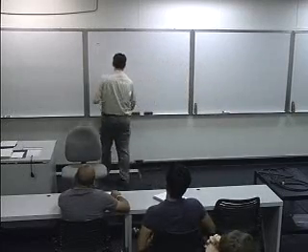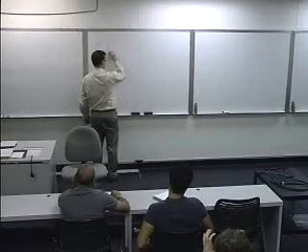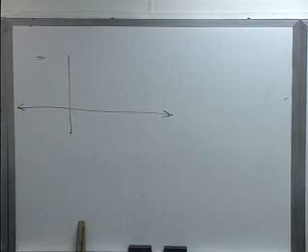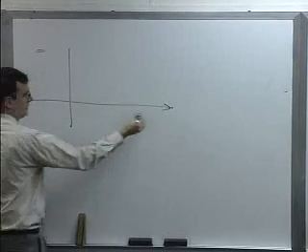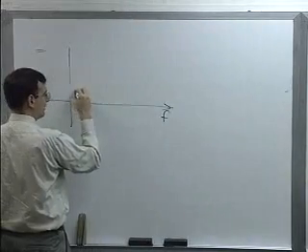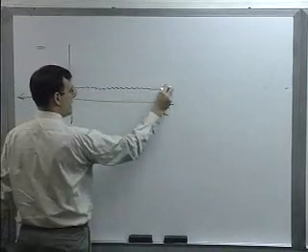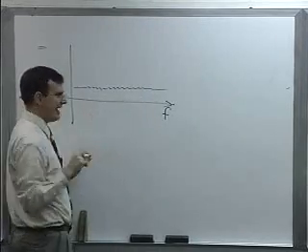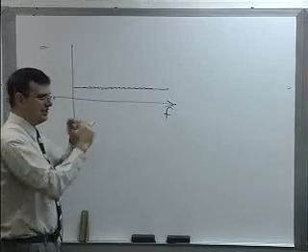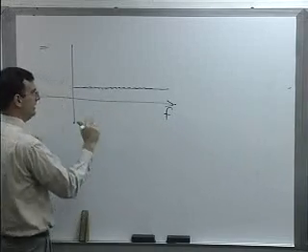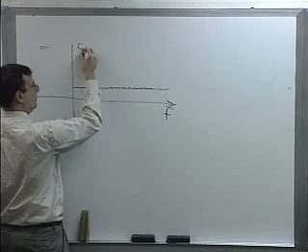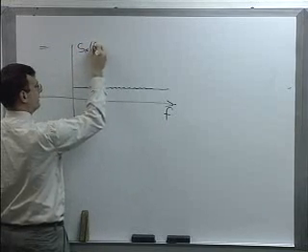Recall that if we looked at it on the spectrum analyzer, in the frequency domain, over the RF bandwidth it would look like a flat, what we call white Gaussian process. This flatness in the frequency domain means that each sample in the time domain is completely uncorrelated. You think of this as the power spectral density of noise. We call it S sub n as a function of f.